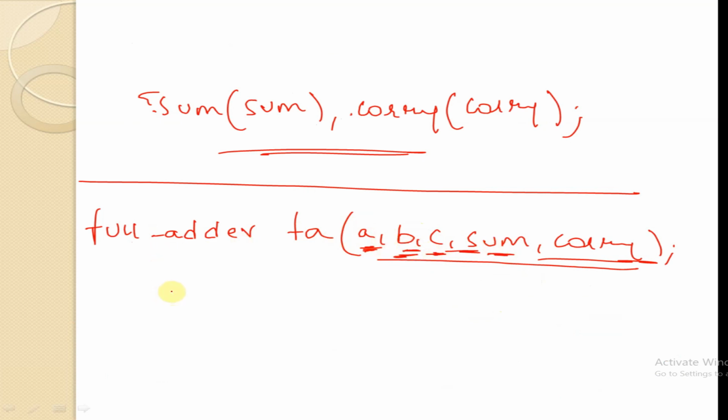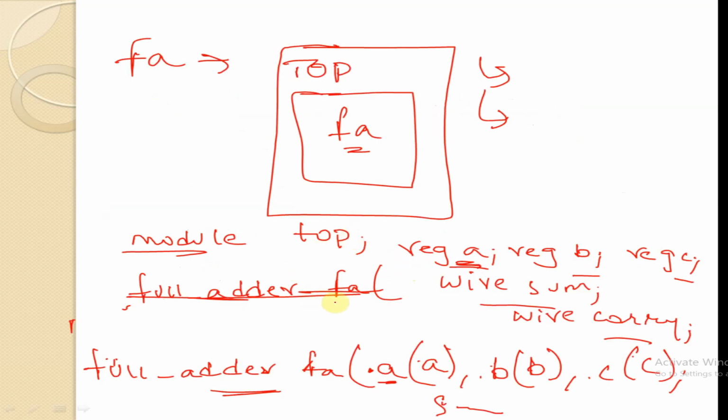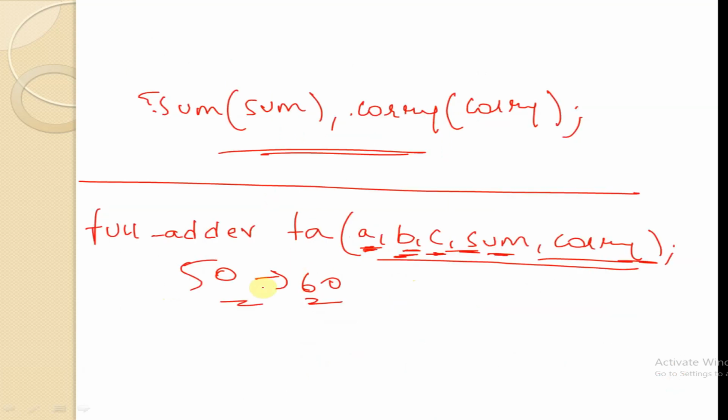While developing a positional based instantiation, we should be careful while instantiating the design. While designing bigger modules, say we have 50 to 60 signals or ports, then we will generally prefer name based instantiation, because if there are this many signals, it is somewhat difficult to remember all the positions of the signals, and there might be some proneness to errors.